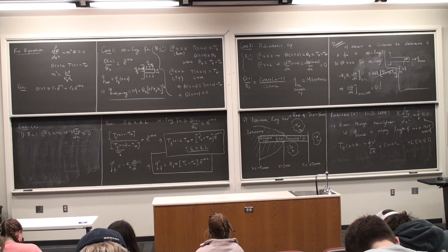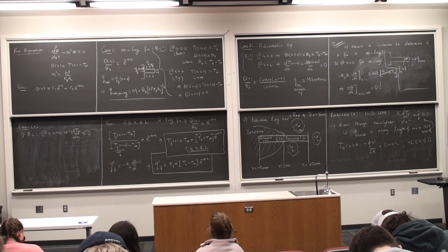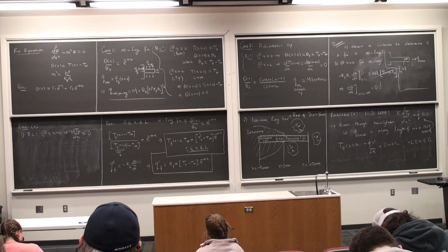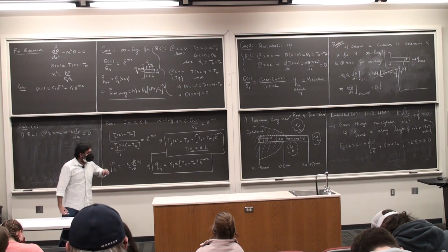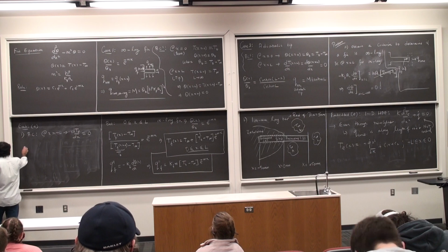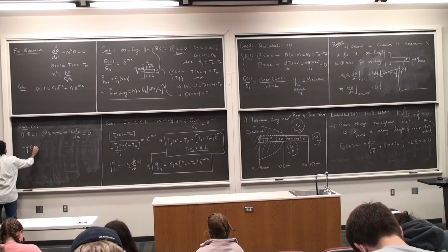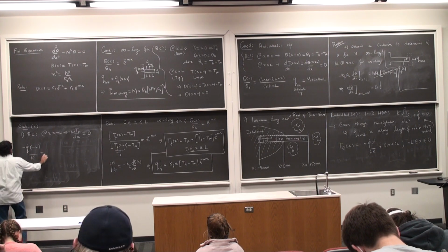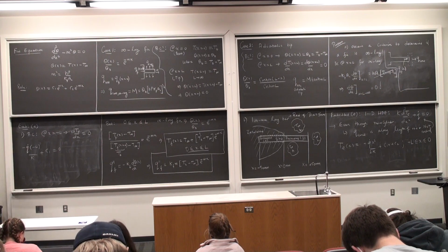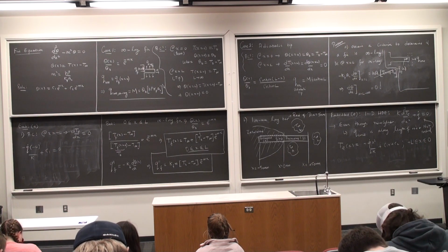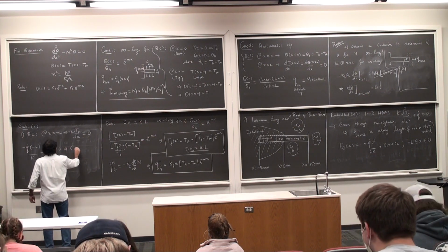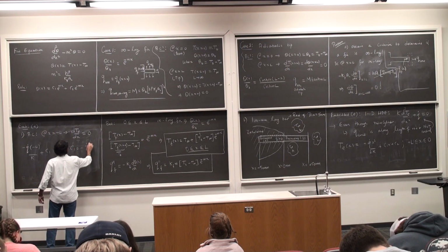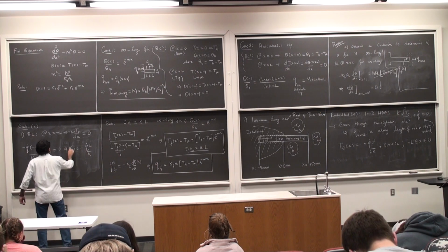So that's the first thing. Let's substitute this, okay? dTE by dx at x is equal to minus L is minus Q dot times minus L by k plus C1 is equal to 0, so I can obtain C1 this way. I know the length, I know Q dot, I know thermal conductivity. So C1 is minus Q dot L by k.